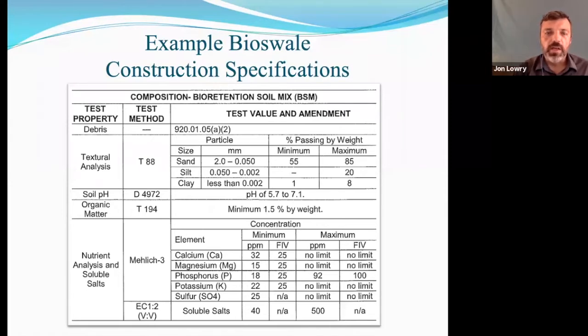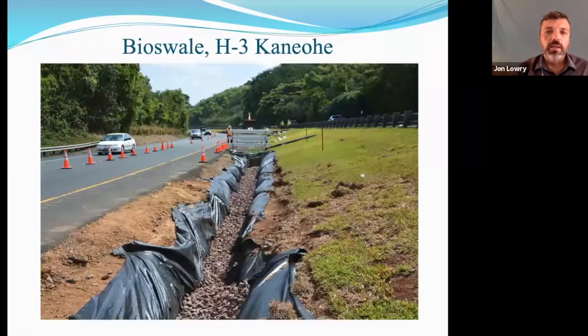And it's also important to note that during construction, it's really important to protect the aggregate layer. We've had instances where during construction, there's a large rain event and fine sediments made it down into the aggregate layer, which really decreases the capacity for storage long-term for these bioswales.